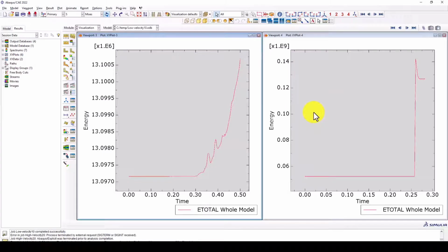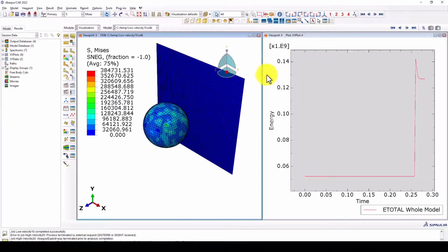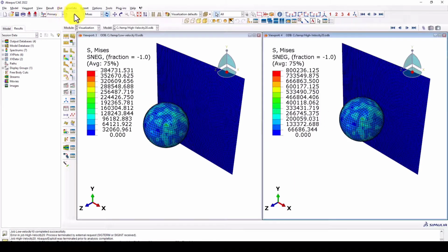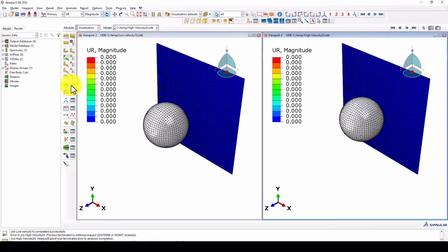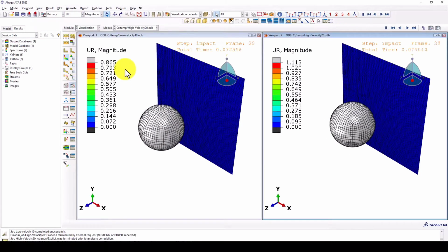Now, let's set up the boundary condition. We are fixing up some edges as I highlighted these. Next, we need to define our boundary condition. The plate cannot simply float freely, as in our physical test the plate is clamped. So we need to represent the actual experimental setup. But be careful, over constraining the model can produce unrealistic stiffness. Under constraining the model can cause unwanted rigid body motion. The boundary condition should represent the physical fixture.